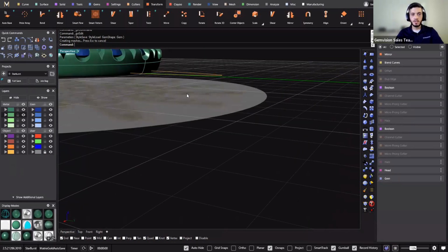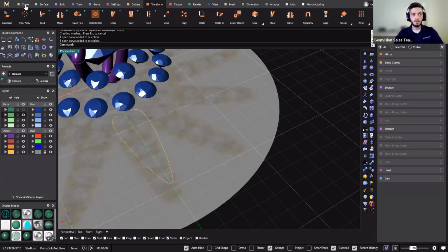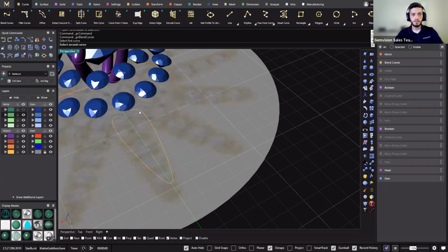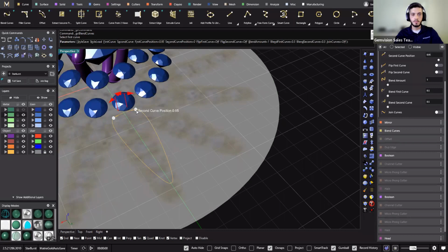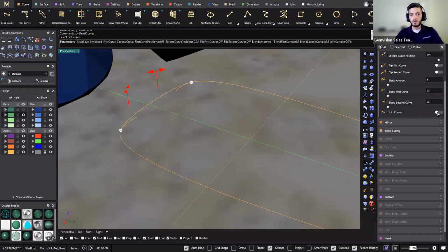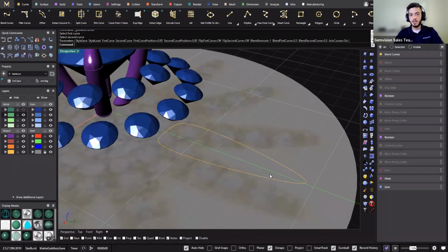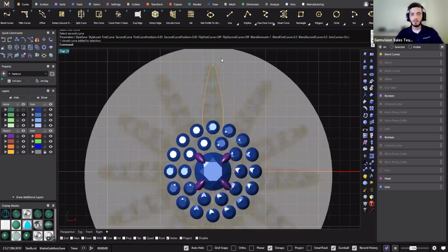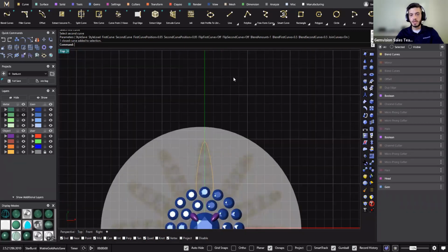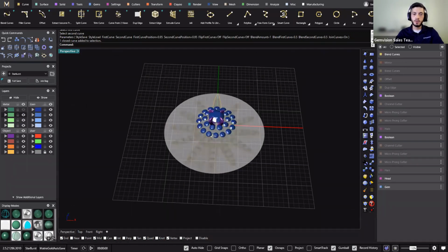So once we have this guy, we can blend one more curve. Bring him down here. And if I toggle join curve, you can see it gets rid of the excess. And if I press enter, I now have a planar curve that's joined in the shape of my, I guess, pedal, I call it. But so once we're here, we have a few options.